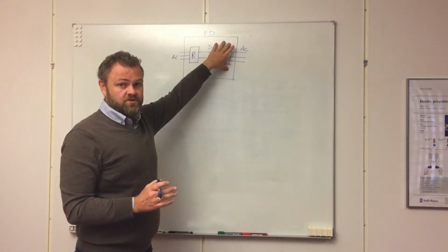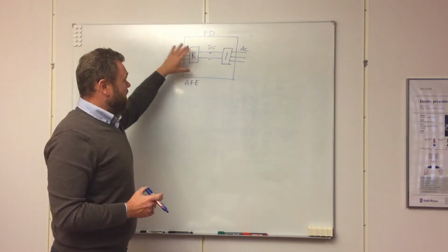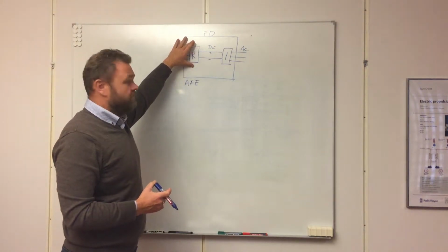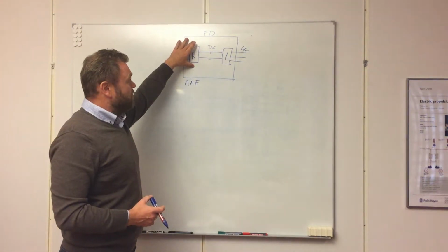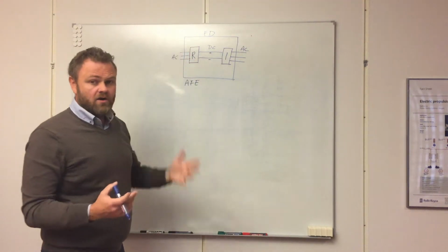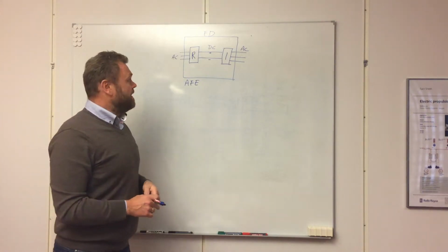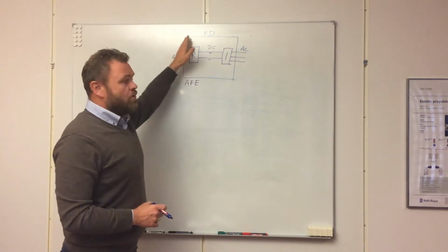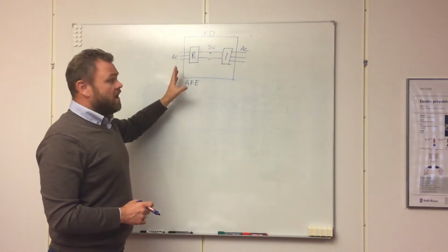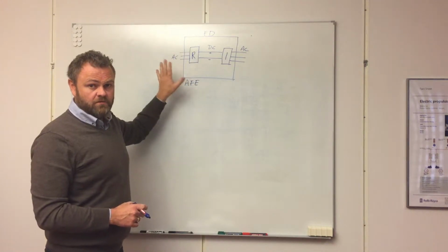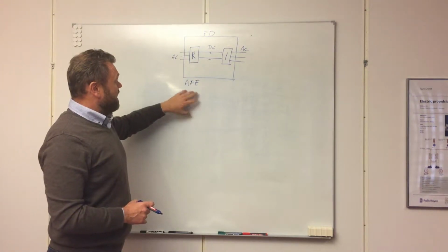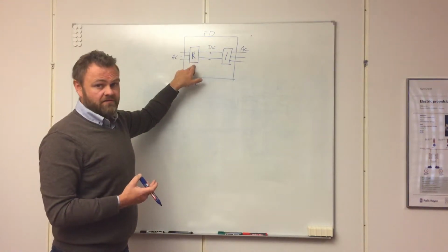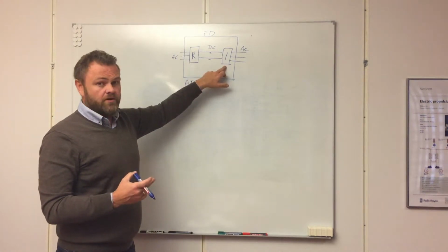So it may be a bit confusing, but if you keep in mind that we tend to use these words a bit different from person to person, you are aware of that, so you can maybe ask a question, what do you mean? So we call the overall cabinet a drive or a frequency drive or a frequency converter. And then we have the frequency converter units inside, the rectifier unit and the inverter unit.